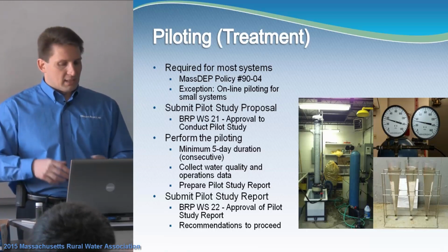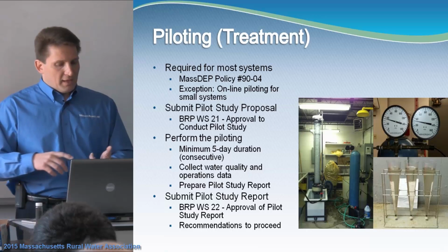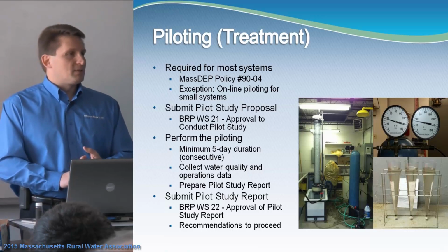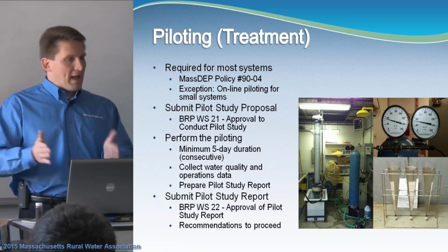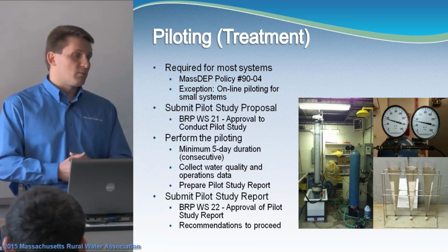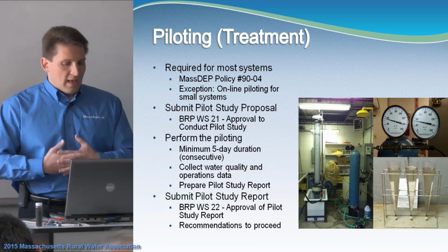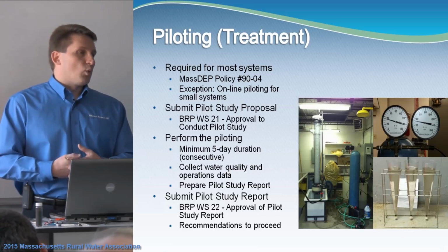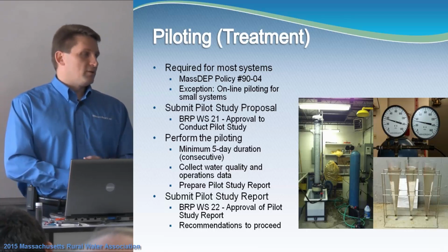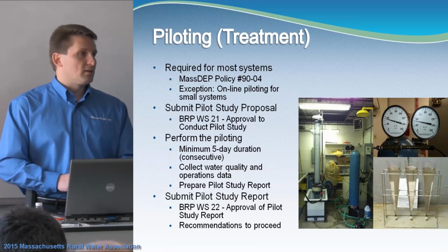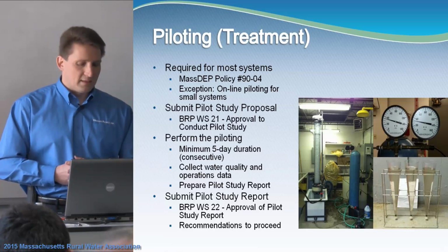And throughout piloting, you need to collect water quality data and operations data. Things like your filter run times. How long does it take before you backwash and then need to backwash again? Because if you're backwashing too much or too frequently, it's probably not going to be a good process, because you're going to be wasting theoretically a lot of water. How well is the treatment process working? Is it removing all of the manganese, most of the manganese, some of the manganese? And then you need to look at your chemical dosages as well, because you want to make sure that you're not overdosing or underdosing. So there's a lot of data that needs to be collected during the pilot study.